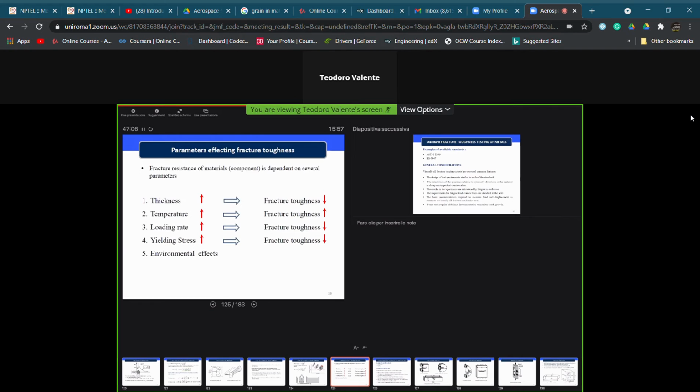And this is also the reason why, for high strength materials, which are used in high performing aerospace applications, most of the time the linear elastic hypothesis, or at least the elastoplastic approach with small scale yielding, can be used for pre-dimensioning of the component itself, because we are in a situation in which the ductility of the material is not so wide, and ductility effects can reasonably be thought to be concentrated essentially at the crack tip.